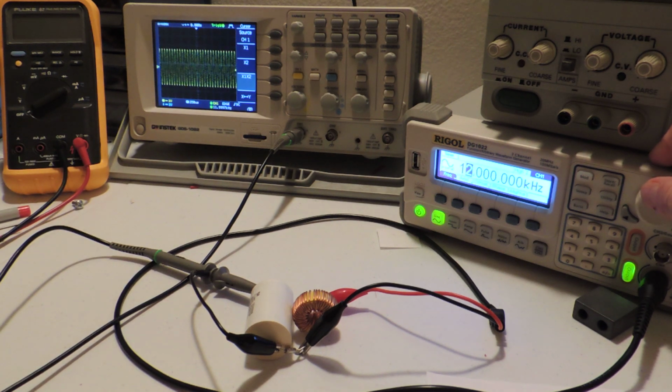As you can see here, we continue to go up, and right as we approached 14 kilohertz, it started to roll off in the other direction. So we will bring it back to right around 14, go one more digit in and adjust it further. And it looks like about 14.5 kilohertz is our magic number.